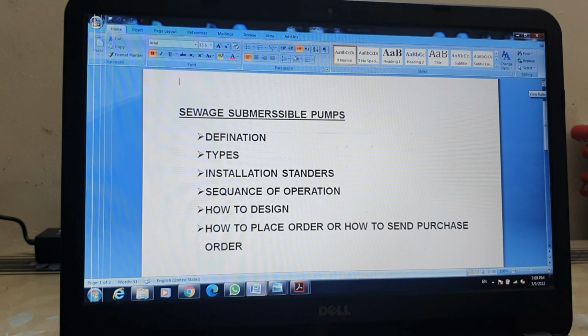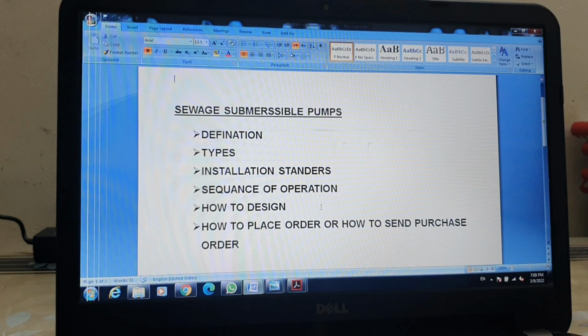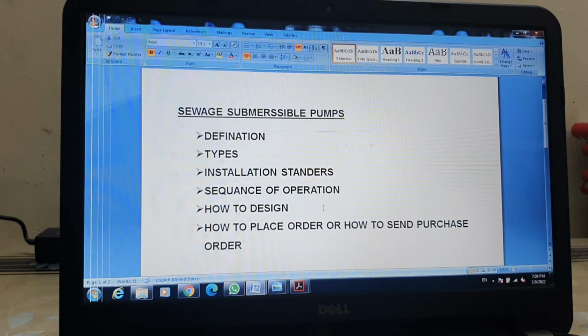I would like to clarify that any equipment in a mechanical system, whether motors, chilled water pumps, water supply pumps, or chillers, any such equipment which is related to mechanical but has a part with electrical, prior to making any order and finalizing the equipment, we must finalize the sequence of operation.